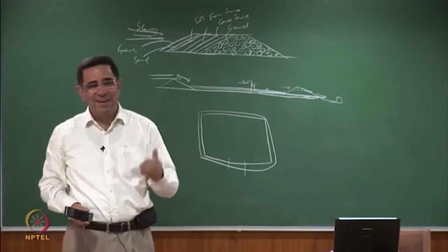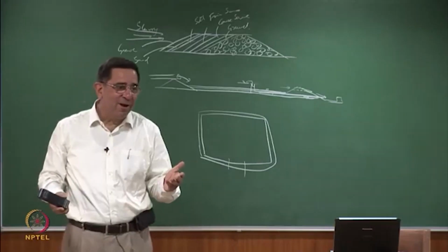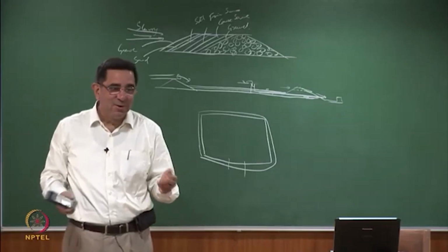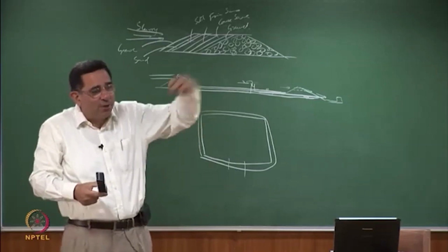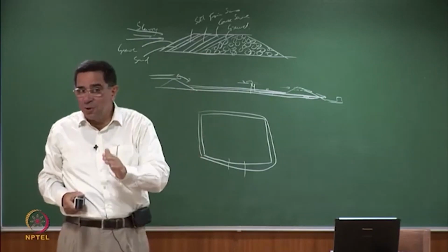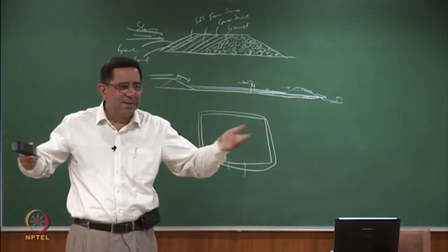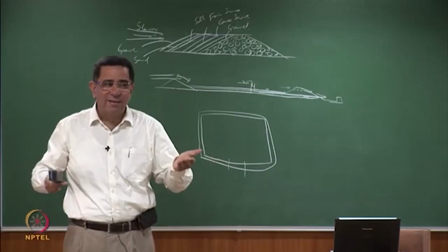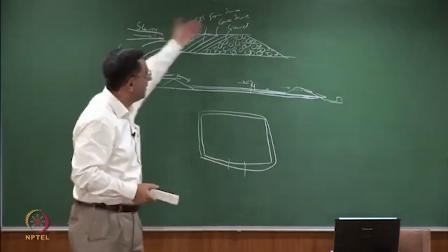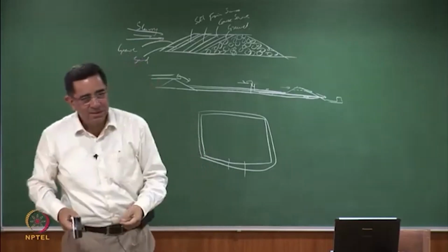Absolutely. Once your fines start to settle, it will start to clog up your drain. You must have the capacity that what is inflowing must flow out, otherwise the water level will rise. So suppose it chokes it, you will say, so what? At least the fines are not going up. Then your water level is rising, and finally what will happen? Water will start flowing over from the top, and again the fines will come out.